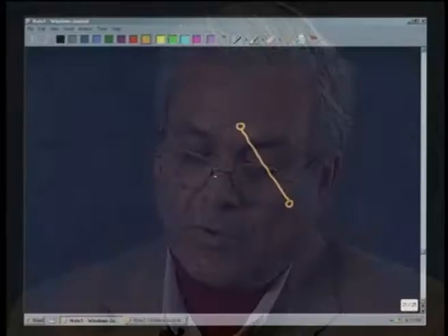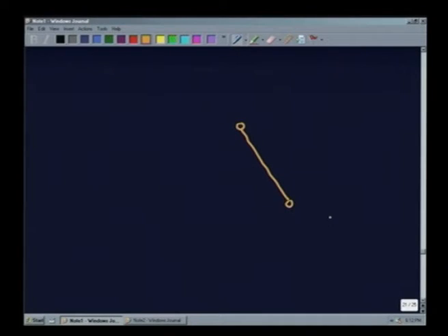Now, this is rotating at a constant angular velocity, and if we do not put in the gravitational forces, then the moment acting on this from outside is M4, and there is some force here R14, and the force from this is equal and opposite to R43, whose one component we have found out.